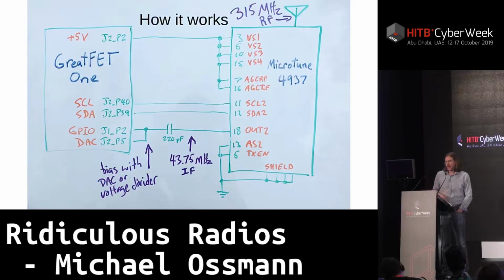And we're sampling that signal with a GPIO pin that we were operating at less than 43 megahertz, which is kind of cool because we were doing a trick that's known as undersampling. We were sampling at a speed that was lower than the frequency we were sampling, and that works just fine, generally, with some limits. But we were also doing another trick called oversampling, and specifically oversampling and decimating. And this is the key thing to understand, to know how it's possible to build a radio receiver out of a 1-bit sampler, a 1-bit ADC.